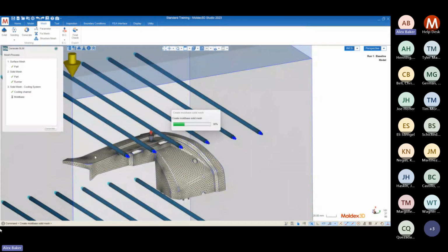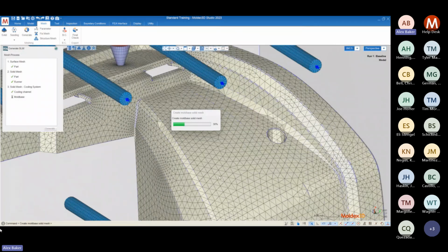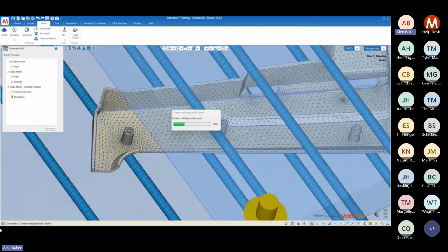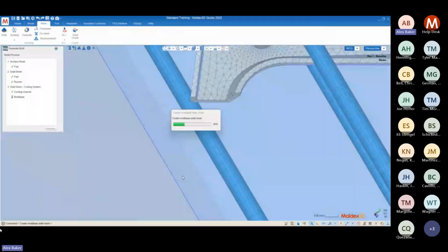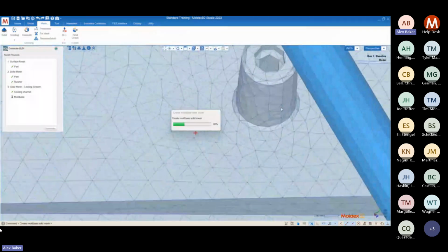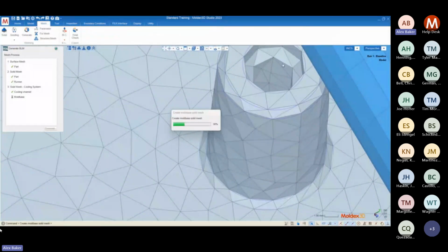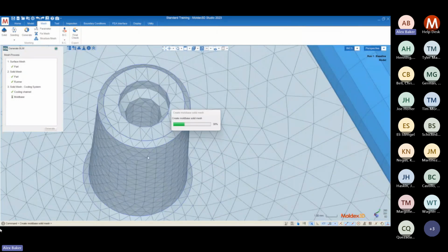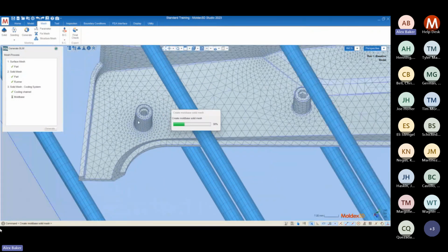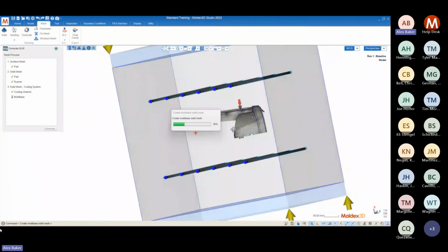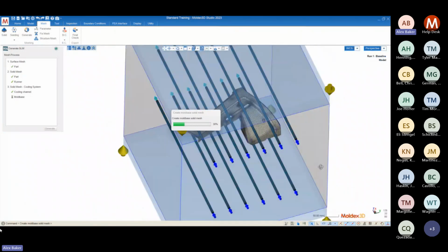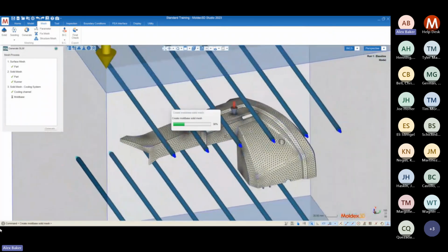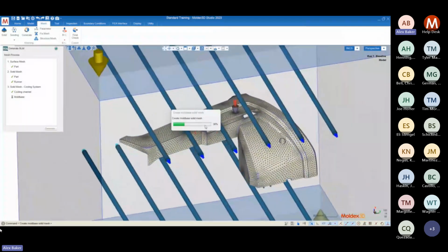Now, the mesh that's created here, we get our surface mesh, which again looks like a bunch of triangular surface mesh elements. We go to the bottom here, we can see that refinement take hold. You see 6 nodes. We see a hexagon around the middle of this boss that I did not refine. You can see that refinement actually does clean up that feature quite a bit. The 5 layers BLM is going to be created through the thickness of our parts, which we don't see here. We will break open the mesh to see that in just a moment here.